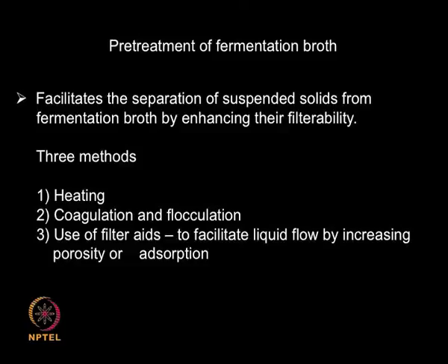This pretreatment strategy improves the filterability of the broth, because if you recall, after the fermentation the broth may be highly viscous. The broth will contain several types of particles: sticky particles, sand like particles, precipitated salts, dead biomass, metabolites. So you need to improve the filterability, otherwise the whole material may spoil the filtration unit as well as slow down the filtration process.